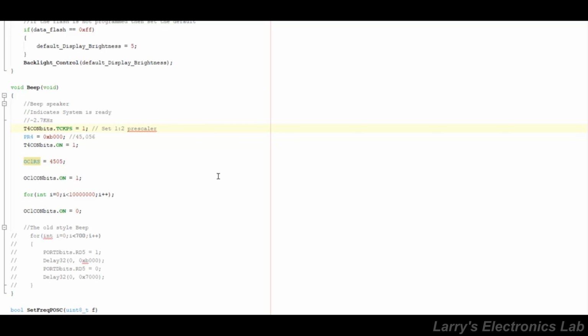So we just showed that changing the duty cycle doesn't change the tone of the buzzer, of the sound. So let's go back to our code, and we'll change the frequency and keep the duty cycle 10%, and we'll reduce the frequency and see what kind of sound we get from it. Okay, so now let's vary the frequency over time. So this is a fairly long beep. So let's take and run this into a for loop.